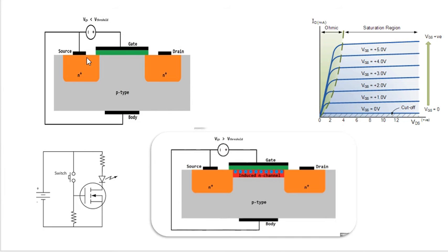At that time we also have to connect drain and source to the power supply voltage. Now you can see in the next diagram, when we have provided a gate to source voltage higher than the rated threshold of that particular MOSFET, a channel is induced. Now when you provide drain to source supply, conduction will take place, and current will flow through this kind of MOSFET.